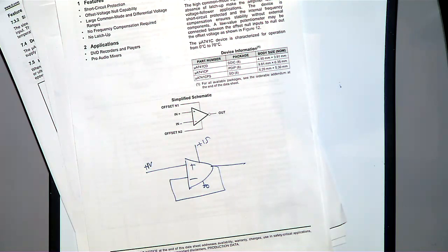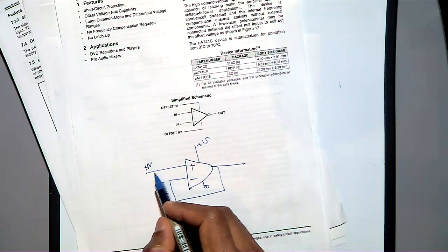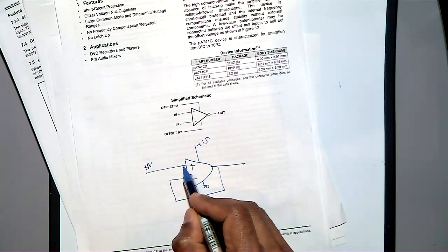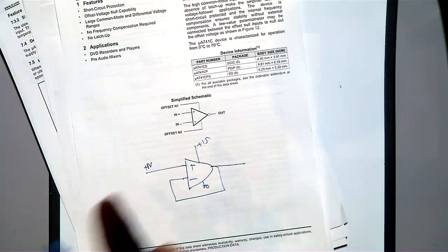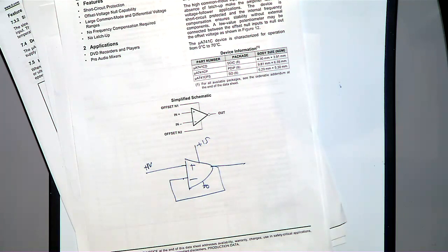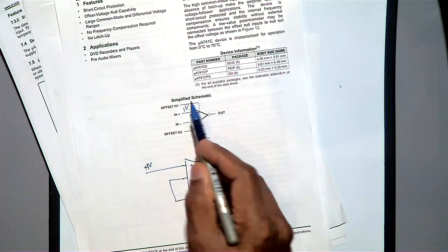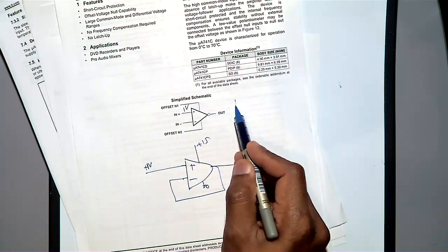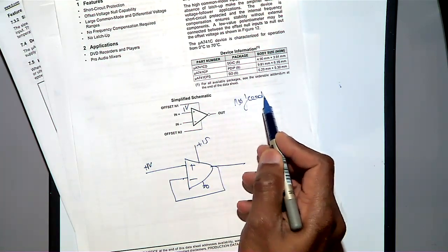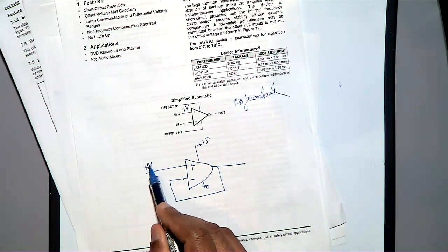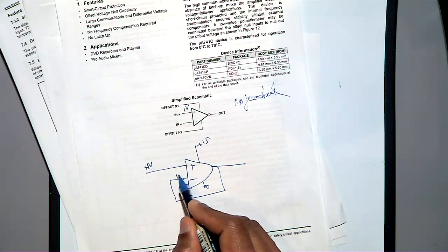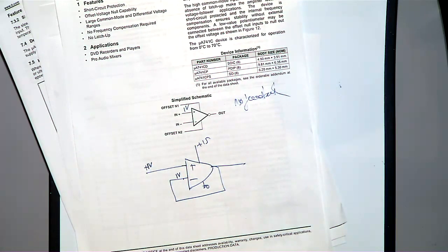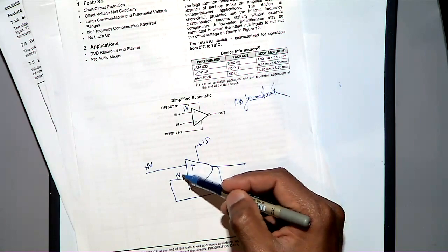Two answers, 15 or 1. Yeah, 1 volt, because you have got a negative feedback. So the operational amplifier will make sure that this voltage equals this voltage, only when there is a feedback, not in the open loop. Because when you have open loop, if I connect 1 volt here, then you don't get 1 volt here, because there is no feedback. So when you have negative feedback and you give 1 volt to this input, the operational amplifier will make sure that this is also 1 volt. Then it's called virtual short.